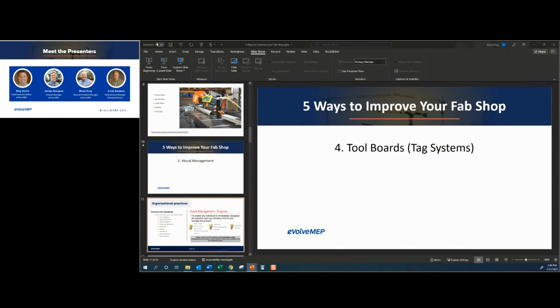Right. And we're pretty fortunate because we've got enough area. We don't like changing shoes over on the benders. We like the stations to focus on that size pipe, and that's helped tremendously too, just not having all the shoe changes. Yeah, the setup of the machine, changing the shoes, takes an awful lot of time.